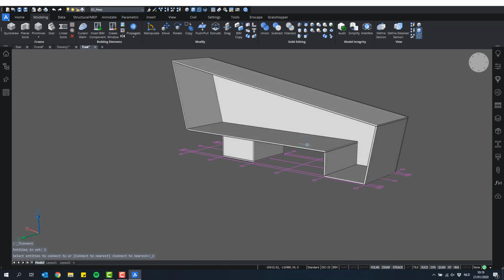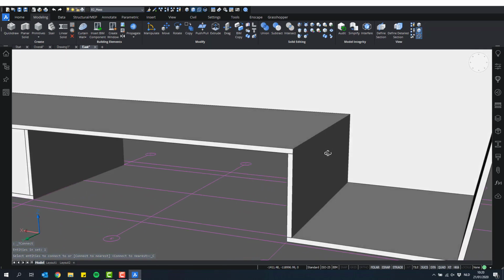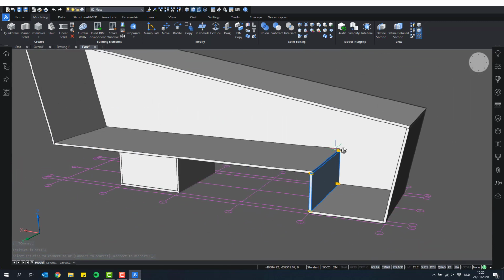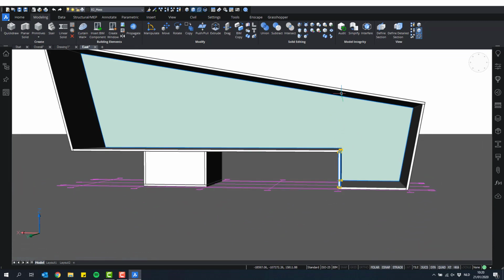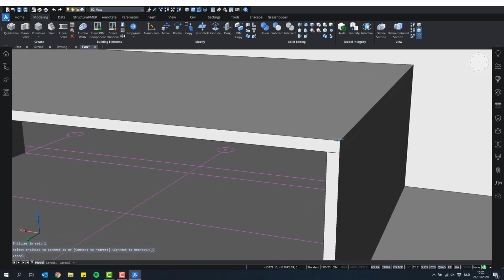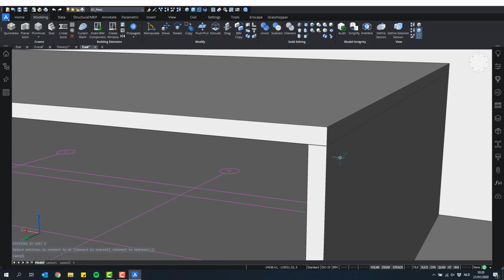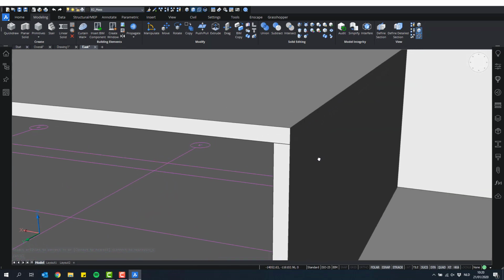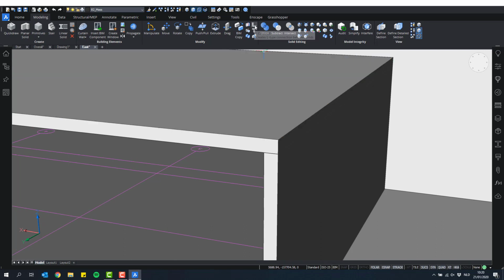I can use the same technique. Let's say I want to have this wall go all the way up here. The easiest way to do this is first I can change my connection here. There's kind of an L connection between this floor slab and this wall. There's a tool called L Connect in the ribbon. If I click this L Connect tool, I can choose my 2 solids, so not the faces but the solids. So I can hold down Control for the solids.